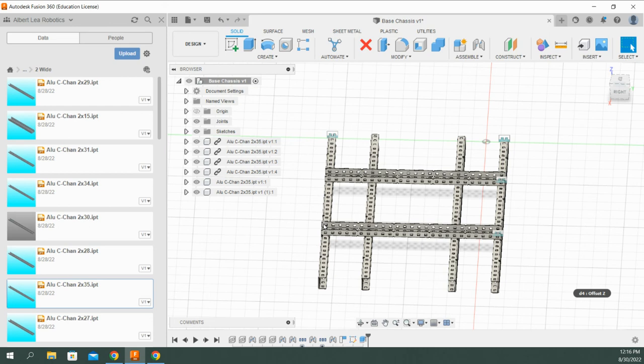If I did it just by distance, say I only cut off 2 inches or only cut off 1 inch, then when I change the distance from 16 inches to 12 inches, I've got to cut another 4 inches off. So I'd have to go back in and recut those inches. If you do it to the face, you don't have to do that.